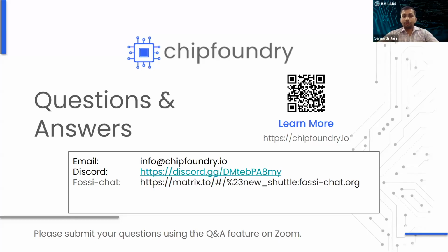I think the user might be getting confused, it's not an SRAM macro, it's a non-volatile memory. So when you are reading, the data remains in the array unless you rewrite it with fresh data. You are just filling the FIFO when you read a particular address, but the data still remains in the crossbar, not in the FIFO. It is erased from the FIFO.